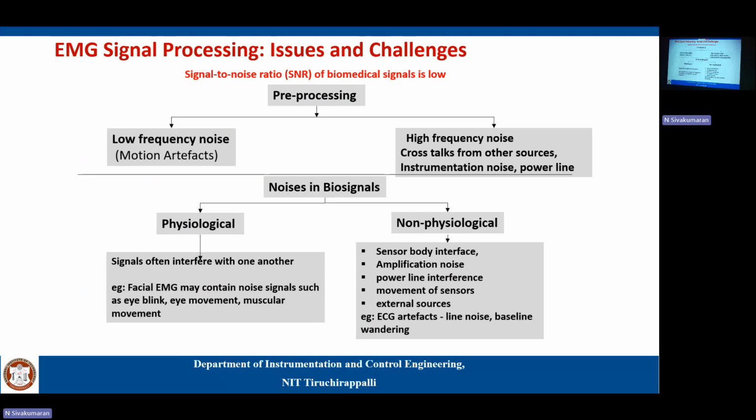Power line interference, most of the time we cannot avoid, even if you do proper shielding and cabling, because this does not need any medium. Electromagnetic interference, for example, if you use your mobile phone close to your electronic system, definitely that also will contribute some noise. So power line, yes.